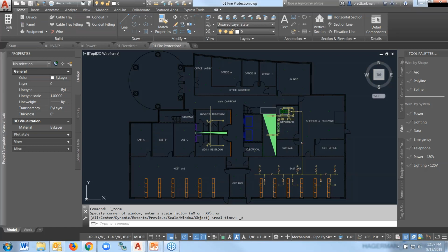You could also have an architectural drawing that you pulled in from Revit, an output from Revit, and put it in as a background, also as an XREF. When you have the 2D drawing from AutoCAD or the Revit drawing, AutoCAD Architecture doesn't have the intelligence of those rooms. So things like when he was doing the outlets around Office C would not work, because there's no architectural space for it to find the room boundaries. So you'd lose some features, but for the most part it will work without any issues. Right, you would have to add the rooms back in on the architect.